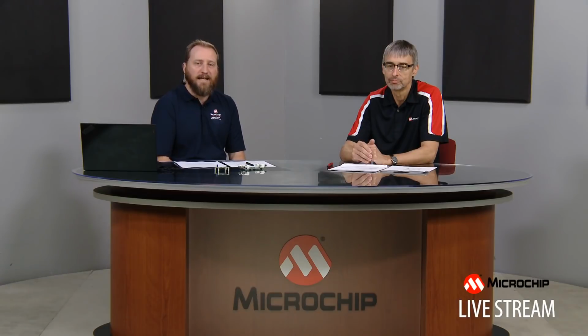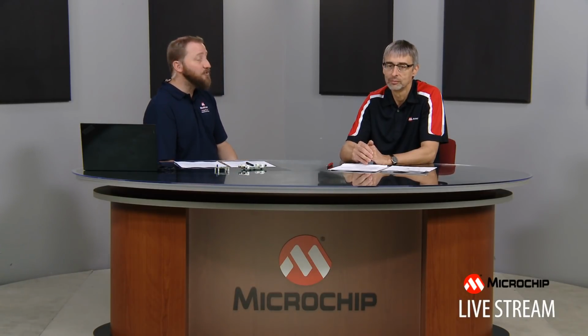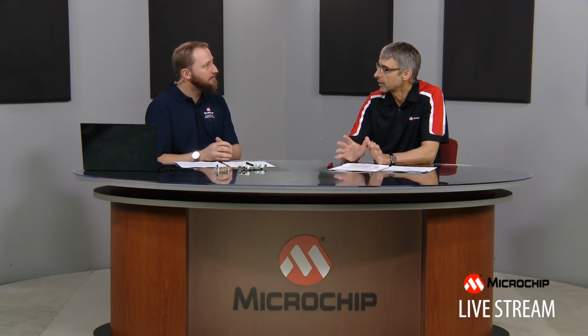Suppliers are a little bit optimistic by saying zero drift. Obviously, it's not zero, but it is extremely low. In a lot of cases, low enough to where a system designer can just assume that it's zero, right? Yes, absolutely. I think it's important to point out that the drift specifications are by now that low that even thermocouple effects on the PC board come into play. So sometimes, the drift of the amplifier itself gets buried by other effects. So that makes it almost zero.